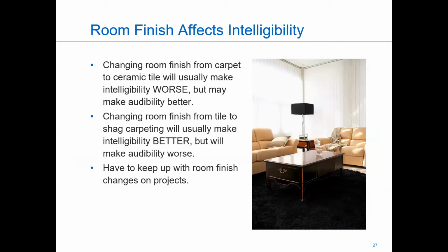Everything affects intelligibility. Exterior, when we're talking about exterior audibility and intelligibility specifically, the temperature, the weather conditions, all the trees, the topography of the location, all are going to affect intelligibility. The same goes for interior intelligibility. And this is where that sound modeling software comes in again. The finish of the room, the ceiling, the heights, what's on the windows, the rugs, the floor type, furniture, all will have a huge effect on intelligibility.